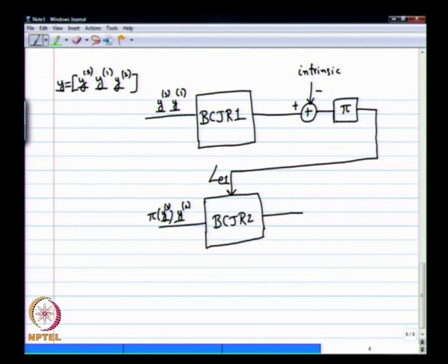If you can use the extrinsic information, then it will produce some LLR which is going to be better than BCJR2 working by itself. So you first get YS and Y1, run BCJR1, and get some LLRs for each of your systematic message bits. You subtract the intrinsic component from that.